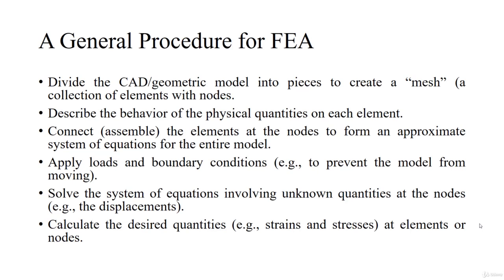In order to solve the set of equations, there are a lot of types of solving methods. You can use the direct solving method for simple problems, you can go for iterative solvers and other sorts of solving techniques. And once you have done all these things, you are going to calculate the displacements at each node. And once you get the displacements at each node, you are going to find out the displacement on the element using what is known as a shape function.